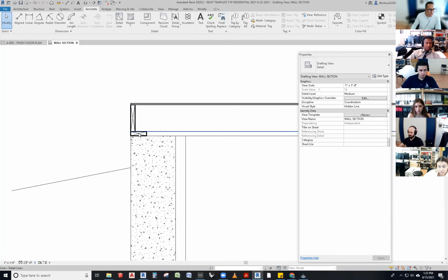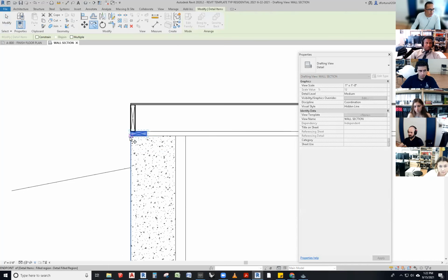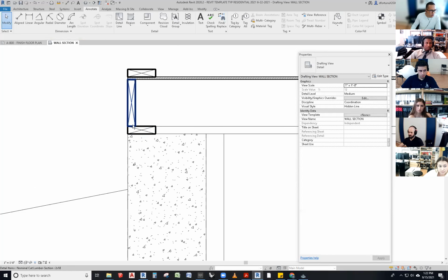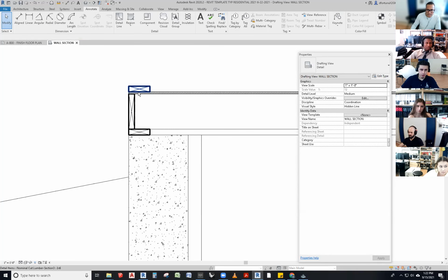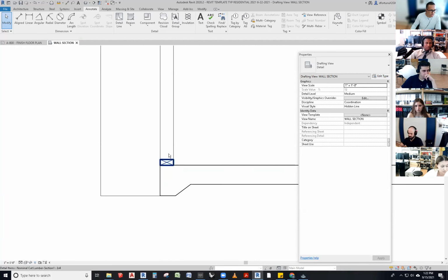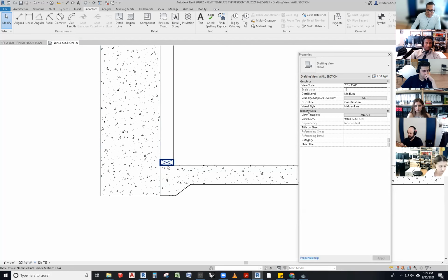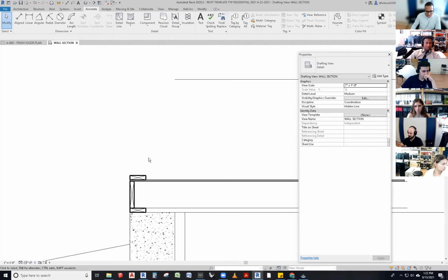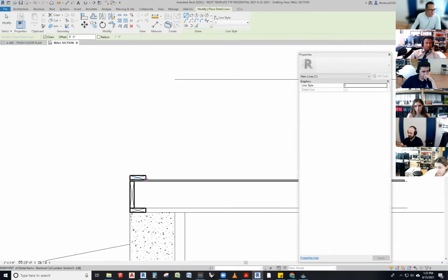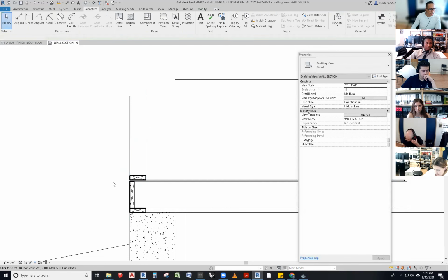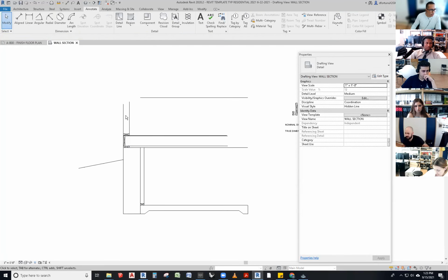So then what else do we have? Well, now we begin to actually frame our wall. We have another plate. So this is the sill or mud plate. This is the bottom plate. This is the band joist. Bottom plate, band joist, sill plate. This is another type of sill plate or mud plate. Okay. Then what do we have? We put our studs that are going to go at 16 inches on center in the other direction. Okay, so that's generally our framing right there.